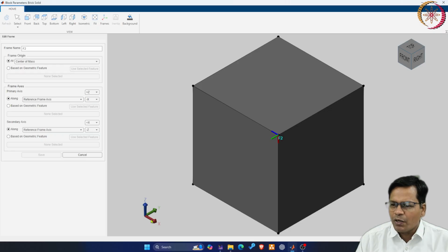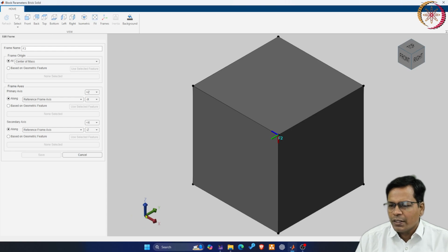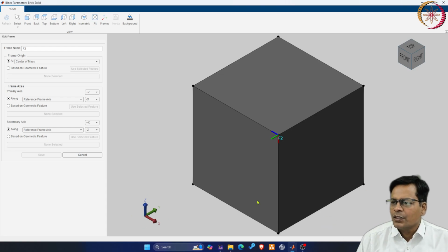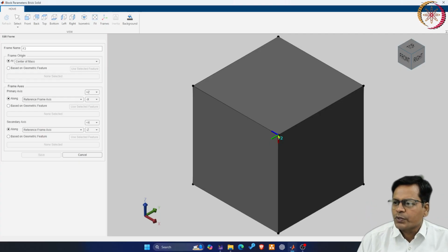Negative of the x axis should be my new z axis, because my robot is directed along the forward x axis. So this is my reference frame, F2. About F2 I will have a moving object which moves along this direction, that is the negative x axis.